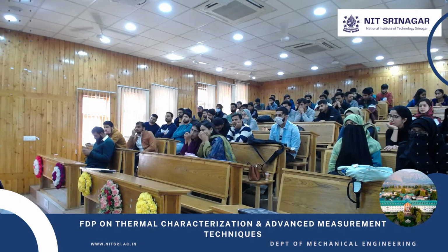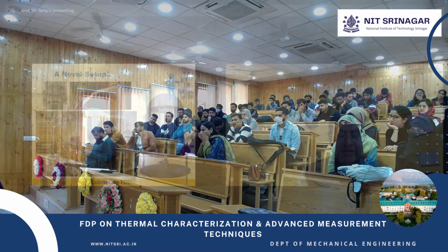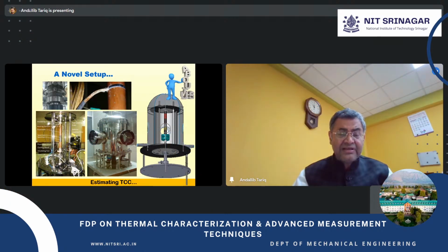And you can see from the top side, a lot of copper pieces are there just to correctly measure the heat flux that is passing through. And this is the actual specimen, say two surfaces, stainless steel or something like that. As I said, one factor is the nominal load, which is applied across the superficial area. From the bottom side, we have an arrangement for applying the load without disturbing the vacuum inside. And some furnace has to be there so that it can heat from the top. The load has to be measured, and heat flow will occur. So there are a lot of complexities, and we have to maintain all the conditions very precisely, scientifically, in control.